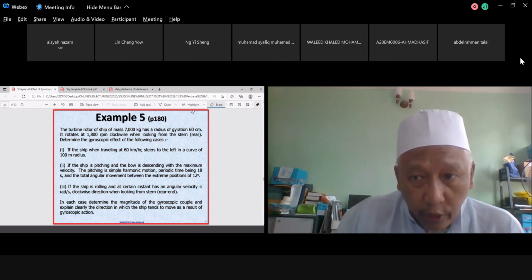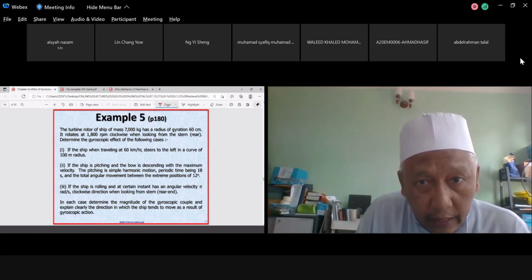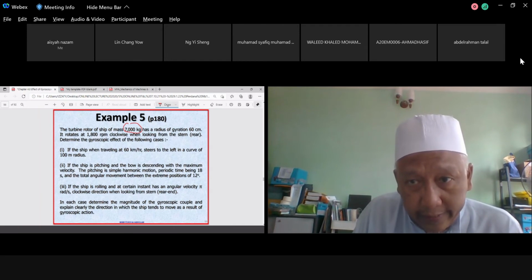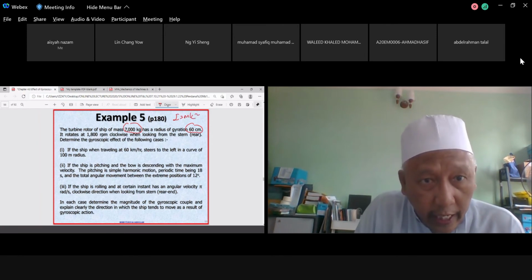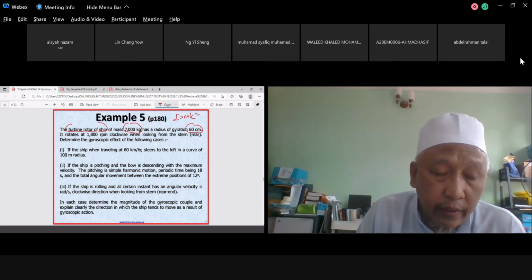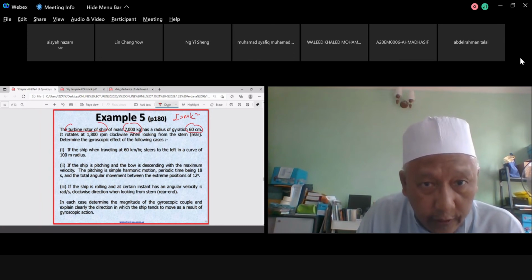Okay, I'm going to read the problem. So you have what you have here: the turbine rotor, 7,000 kg, the weight of the whole thing, radius of gyration 60 cm. This is provided to you; remember, I equals m k squared. And the turbine is rotating with a speed of 1,800 RPM. So this will be your spin velocity.